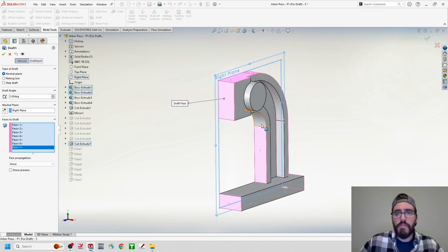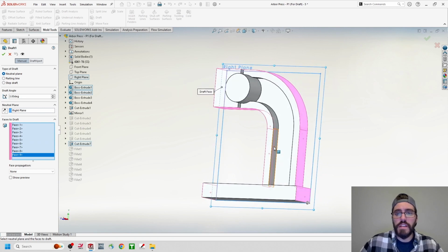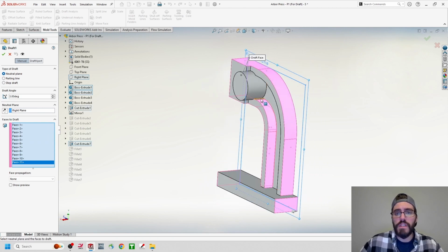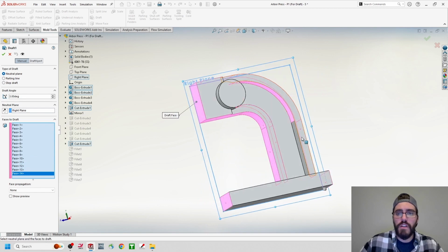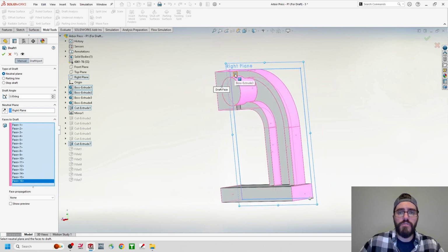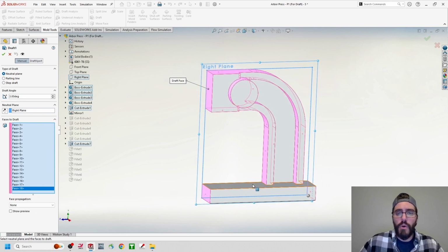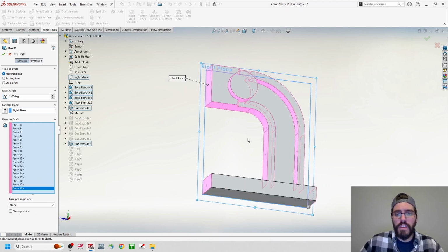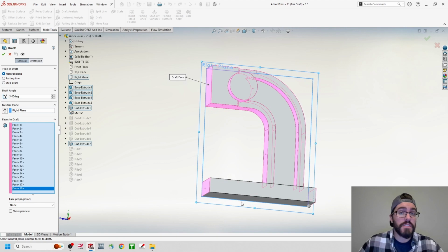So make sure to grab the inside and underneath, as well as this cut extrude that's on the inside here. So we'll click on those, and then there's two sneaky surfaces that you can't see behind that circular profile from certain angles. We'll also grab on that circular profile, and then don't forget the back two faces here from this boss extrude. We don't want to include this top face or the bottom face because they're crucial to the design of this component. We're going to have that surface plate up here, and this has to sit flat on the table. So don't include those two.